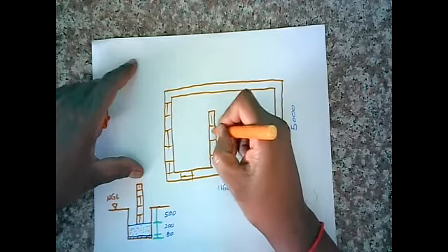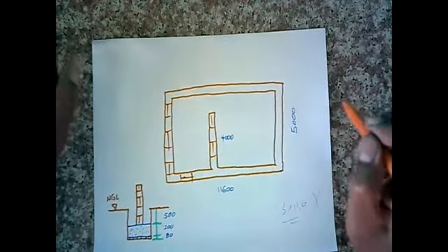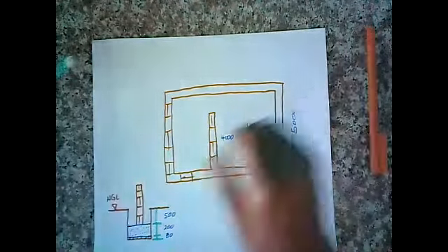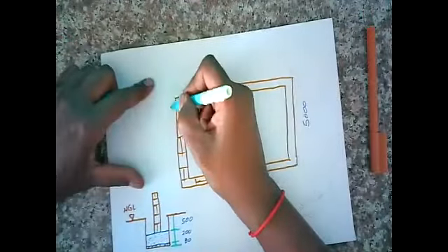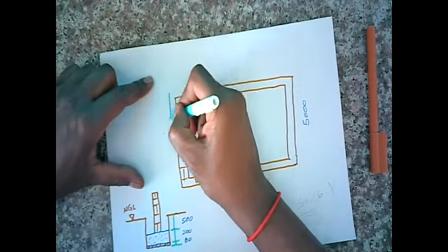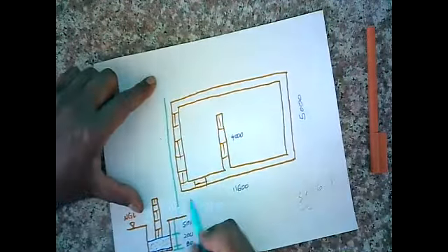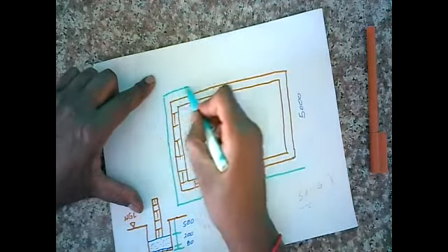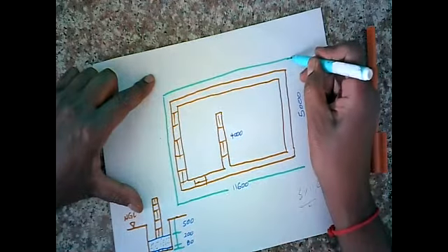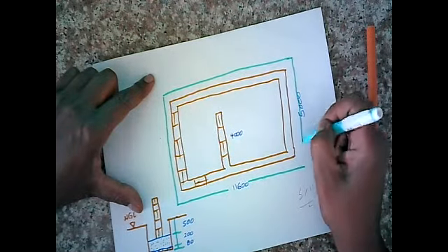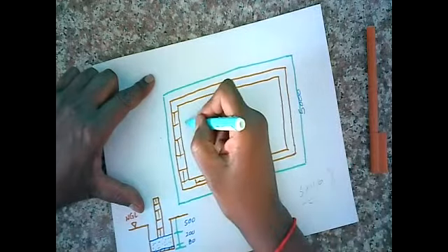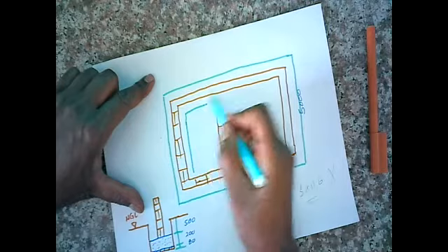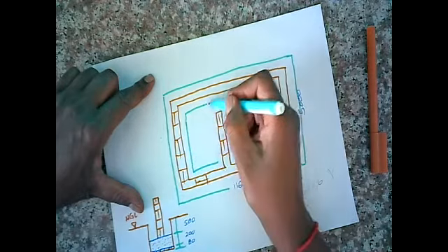Brickwork sits on the foundation, right? So where's the foundation? Now, the foundation lies outside of the brickwork, doesn't it? Now, can you see why the dimensions of your site clearance are completely wrong? It's more than what the diagram shows you, which is something you have to realize.